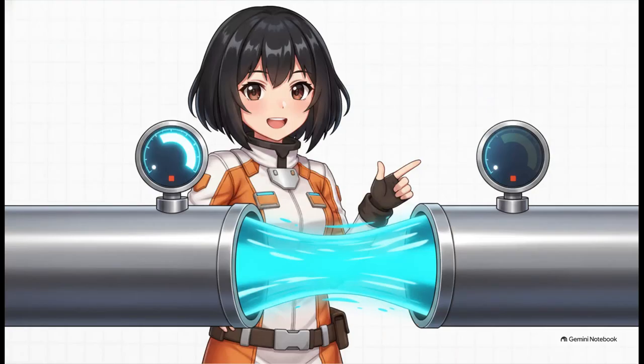A truly foundational concept in differential pressure measurement is Bernoulli's equation. The idea here is that if a fluid flows through a tube and you artificially decrease the tube's diameter, basically creating a restriction, the fluid has to speed up to get through it. And as that velocity increases, the pressure drops. By measuring that differential pressure, meaning the pressure right before the restriction compared to the lowest pressure right at the restriction, we can mathematically calculate the exact flow rate. The flow rate is actually proportional to the square root of that differential pressure.